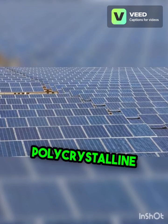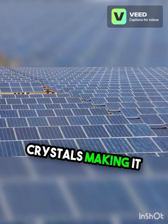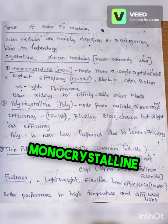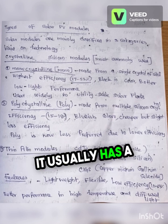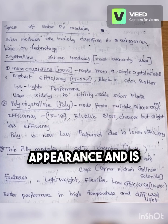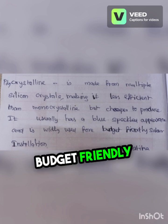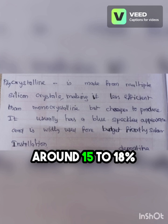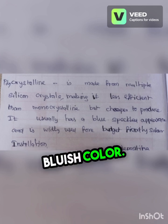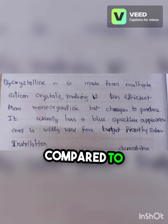Next one is polycrystalline panel. It is made from multiple silicon crystals, making it less efficient than monocrystalline but cheaper to produce. It usually has a blue speckled appearance and is widely used for budget-friendly solar installation, and its efficiency is around 15 to 18%. Blue in color, cheaper but slightly less efficient compared to monocrystalline.